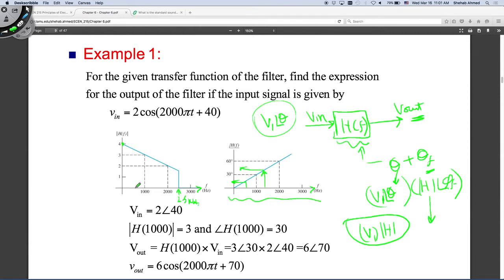Like here, at every frequency the magnitude is different. Right? So here I should have written h of f, for example. Because at every frequency the magnitude is different, and at every frequency the angle is different for a transfer function. And that's what the transfer function does. It changes the magnitude and phase shift of the input, depending on the frequency of the applied signal.